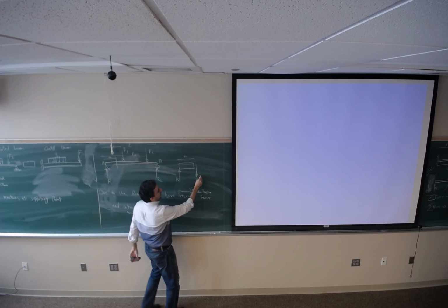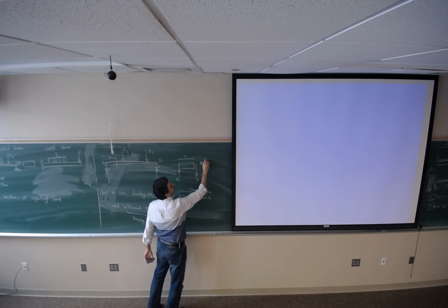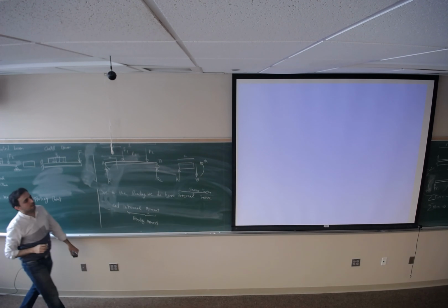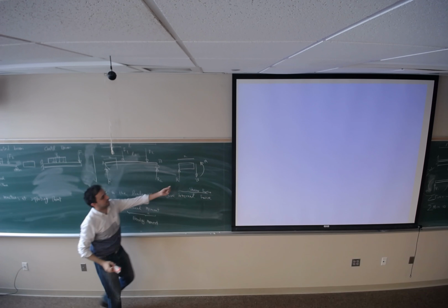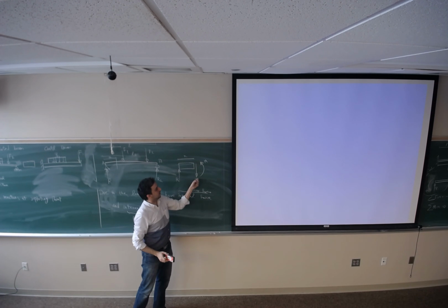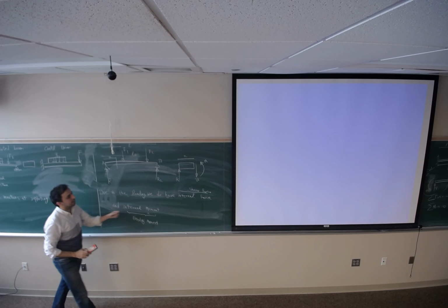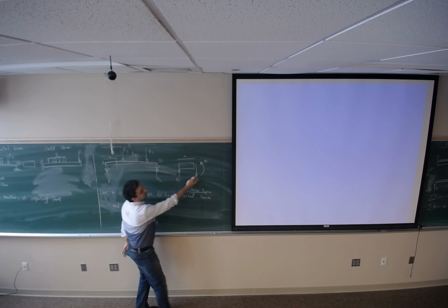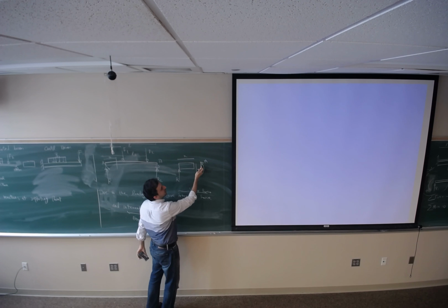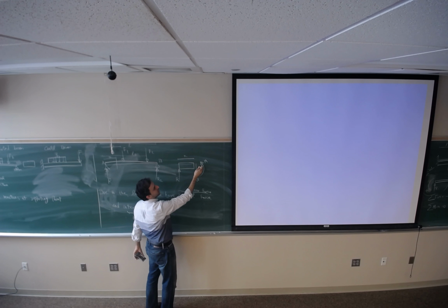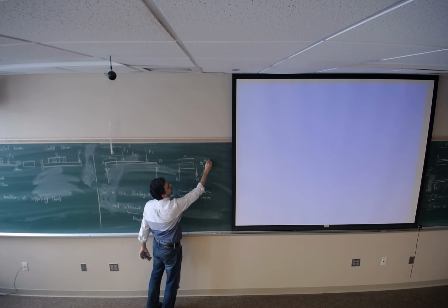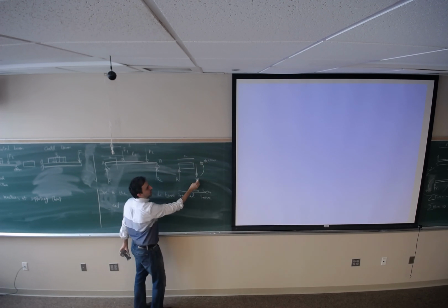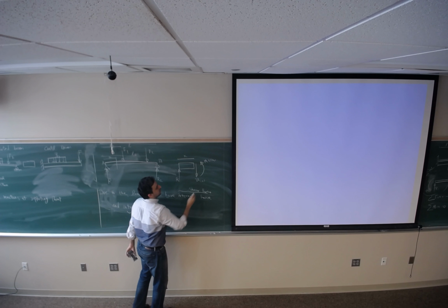And also I'm going to have internal bending moment. This is how I represent the internal shear force and internal bending moment on a section that I cut. I put the arrow such that it's making counterclockwise rotation, as you see. And I put the arrow down for the shear force, because for shear force I consider the downward arrow as positive.